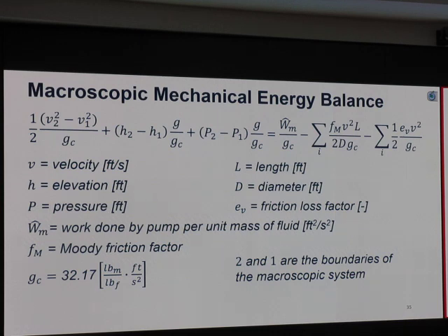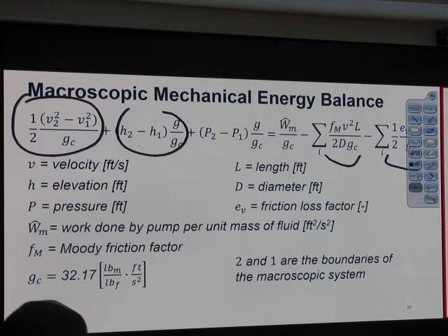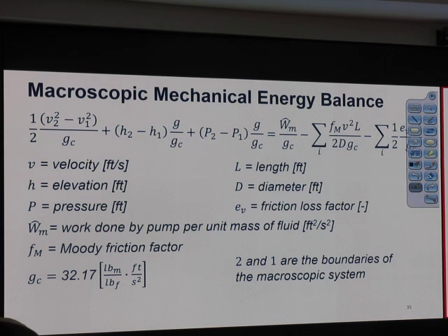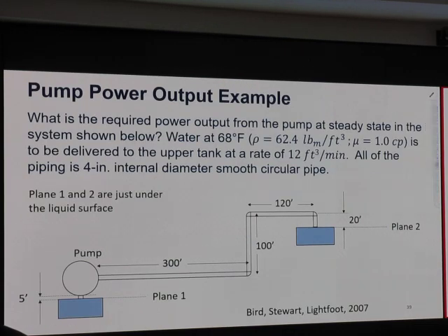Okay. Previously, I had to be told the discharge pressure, right? That equation is easy and quick. But this time, if I don't know how much discharge pressure is required, I can calculate it. Discharge pressure should be enough to overcome frictional pressure loss, accelerational pressure loss, the pressure loss due to the change in the velocity, and the change in the elevation. So this equation takes care of everything. If we already know the required discharge pressure, we don't need to do this. But if we don't know, like in the example that we are about to see, then you have to do that.